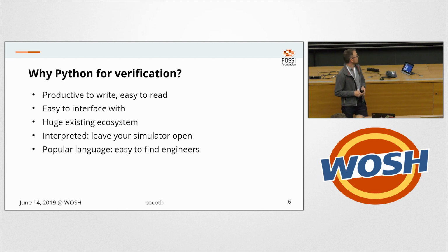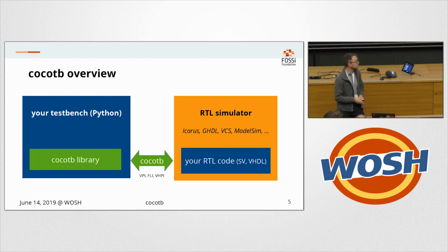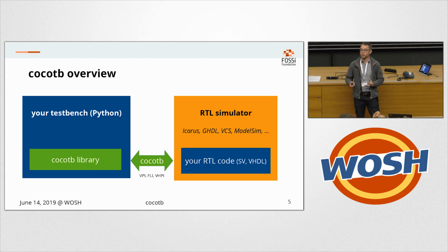The thing that's not mentioned here, and that goes back to that slide, is if you go for UVM, you need to have a commercial, or kind of proprietary, simulator. There is no simulator that can run UVM code that is freely available. Going back to the situation that you want to actually have more people writing tests and doing verification for your code, with Cocotb you can use Icarus, you can use GHDL. If you run in a Verilog subset that Icarus supports, you're fully set and done.